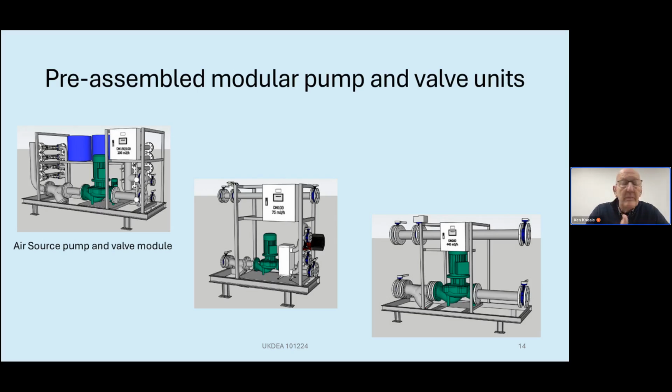We bring out a flow and return from the heat pump to go out to the evaporators, but that is actually divided into 4 so that we can defrost 1/4 of the evaporators without a huge reduction in power output. And the other pump units now that we make in the factory, they are for water source units.